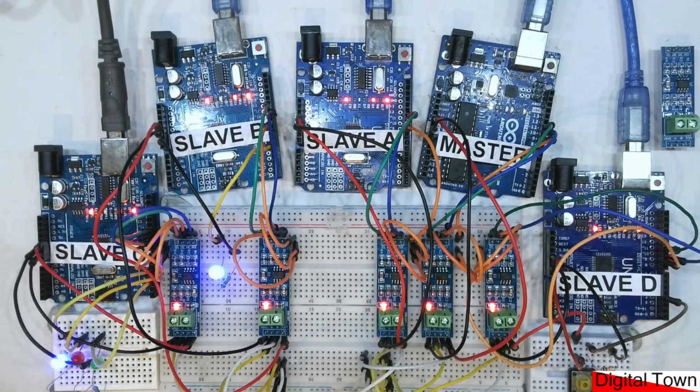So going back to the desktop, you can see now 5 Arduinos all sending communications between each other. Everything is being controlled timing wise by the master, but at the same time all the slaves are able to communicate to each other as well as to that master board. And the great thing about this is I've got 5 boards here, but we could be using up to 32 boards, and that distance between them, yes, I'm just stuck on a breadboard, but there's nothing to stop me having 1.2 kilometers of cable between each one. That is a very, very long distance.